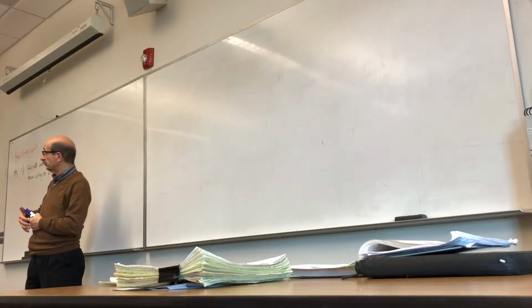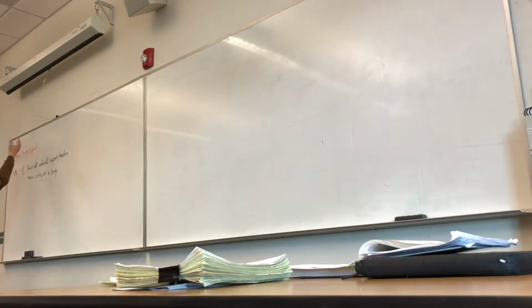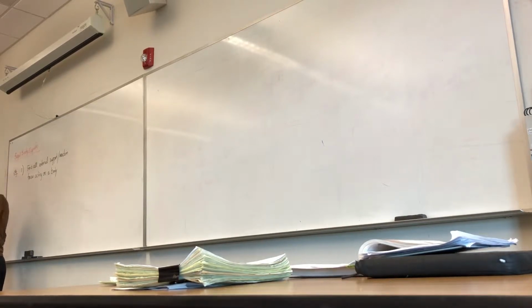You want to design a board or maybe a fixture that holds this board on the wall, right? So you need to know how much force each bolt will carry. You want to build cables or some fixtures to hold this light fixture in place. You need to know how much force each of those supports, being bolts or rivets or whatever, will be subjected to. So we want to find out what are the support reactions that hold the structure in place. That is objective number one in rigid body equilibrium analysis.